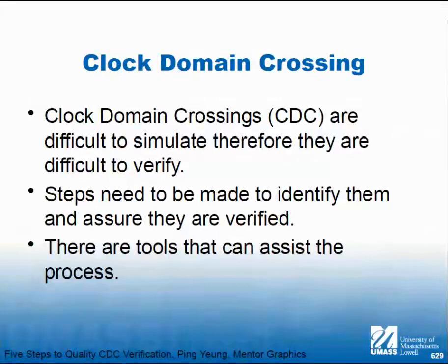So the bottom line here is in the model, it discretely tells you where the setup time and hold time window are defined. And if you're on one side of it, you make the setup time. If you're on the other side of it, you get an error, right? And the error usually comes out as a console error in your simulator that tells you what flip-flop just had a setup time violation.